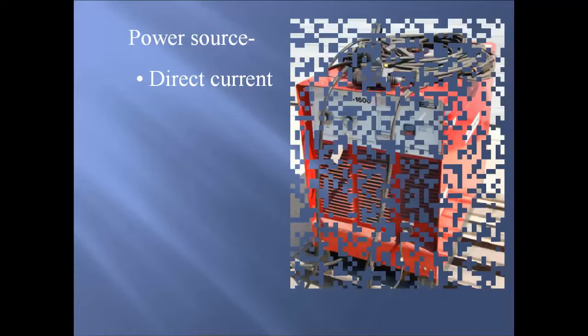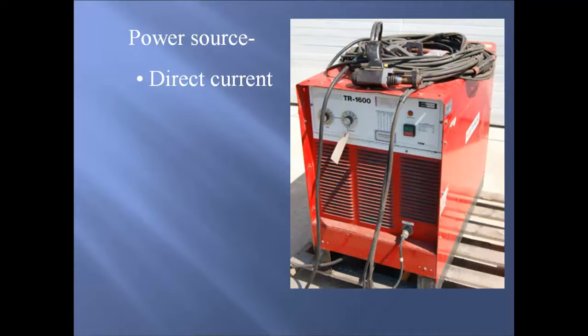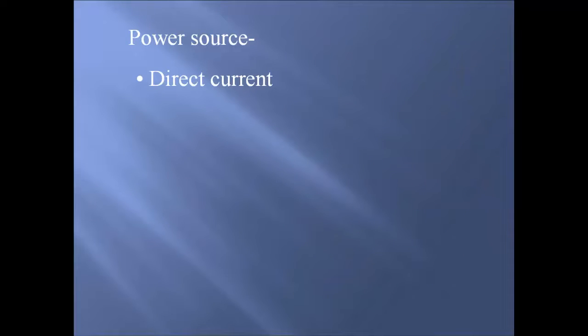We now take a look at the power source required with the stud arc welding process. It will use direct current, and the welding machine is typically like this. This process can use over 2,000 amps at times. This is one reason you need to have an amp volt meter that can register these high amps, and it will be run in direct current electrode negative.